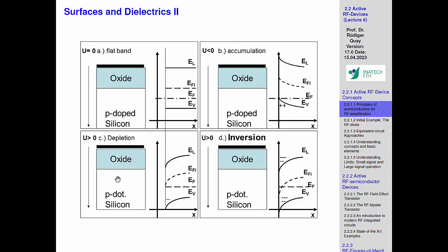The MOSFET takes a very strange idea, which is that you actually want to generate carriers. And the question is, why on earth would there be a carrier generation? Or how would you, when we're in a p-type substrate, why should there be any useful carriers that we can use for something?